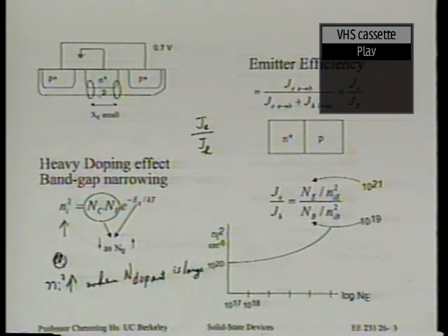And you, as a designer, I think you realize this. If the gain is very poor, let's say 2, nobody can use it for anything. So you have to try very hard to get that gain high. But once the gain is up to a point where it's pretty good, making it even higher doesn't buy you that much. You would rather not push it higher, but use that freedom to make the cutoff frequency higher.